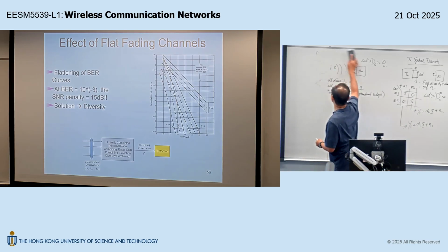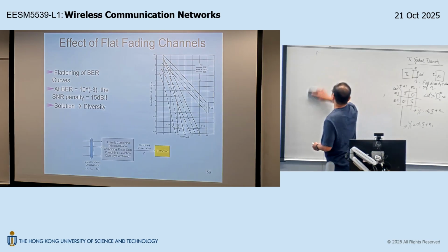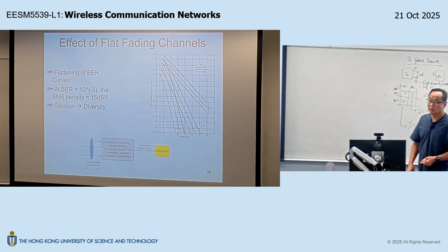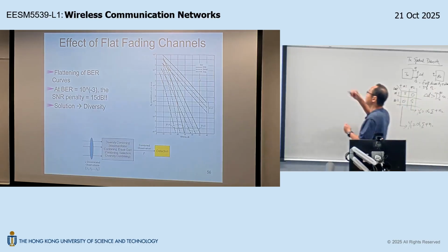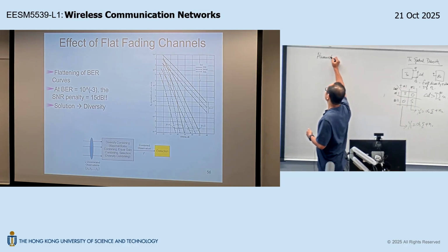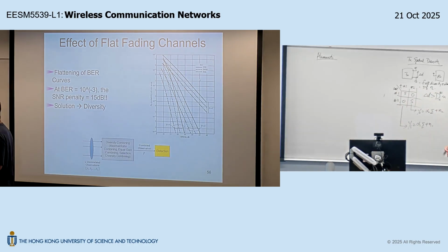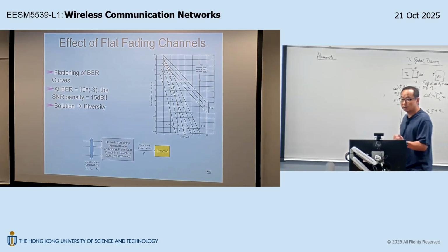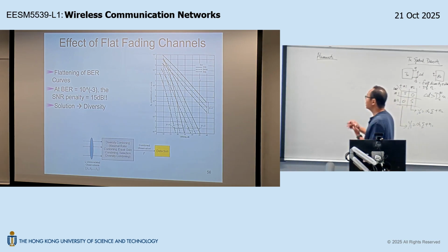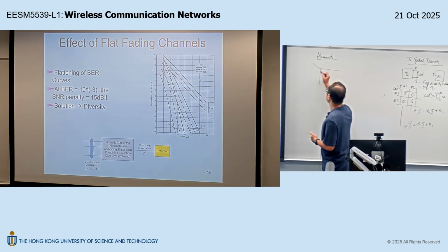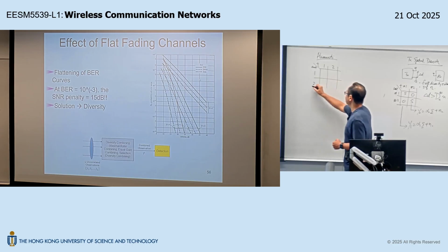let me erase this. Around the late 90s, there was a guy called Alamouti. So he finally found a way to do it, okay? Achieving, with this two transmit antenna topology, full diversity order and 100% spectral efficiency. The way they do it is like this. So this is time, this is antenna. You still need to use the time slots, you still need to engage in two transmissions. Okay, but the way they do it is like this.